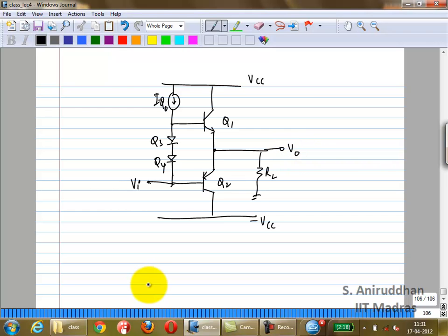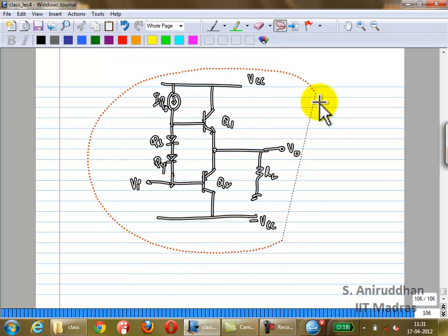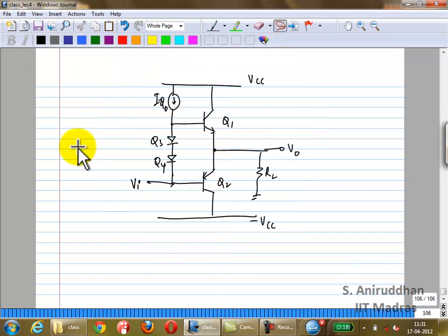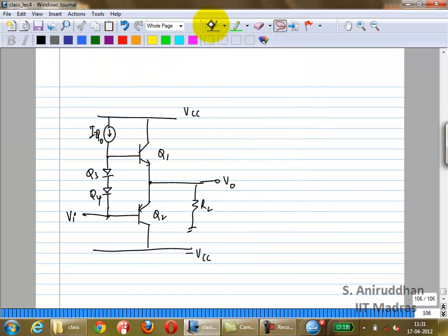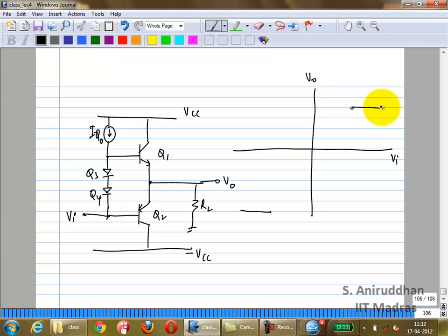So now what will the transfer characteristic look like if you had to draw it? Let me move this to the side. What is this going to look like? I assume for very large inputs it won't change much. All you have done is a small level shift, right? You would think that for large signals it shouldn't change the characteristic. You are trying to solve only the crossover distortion.